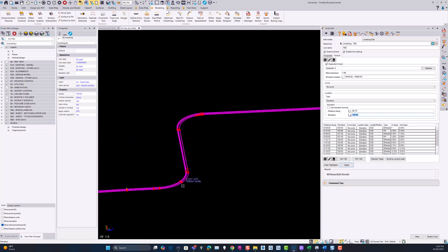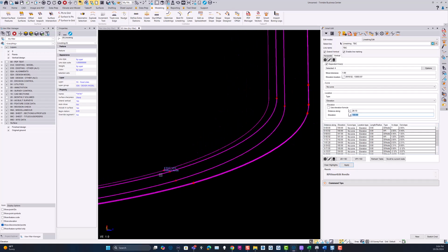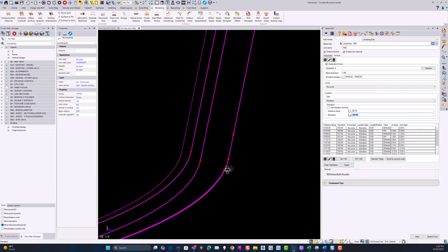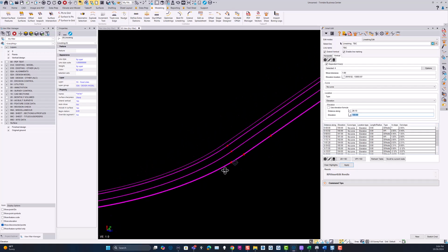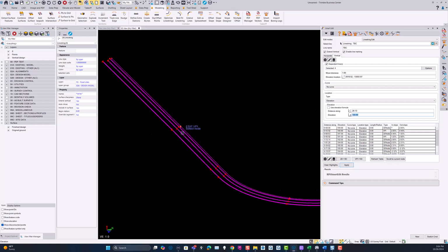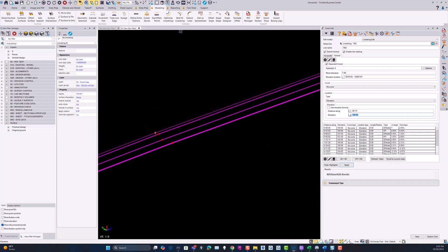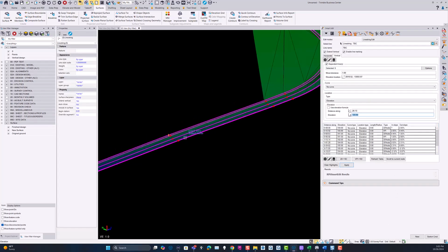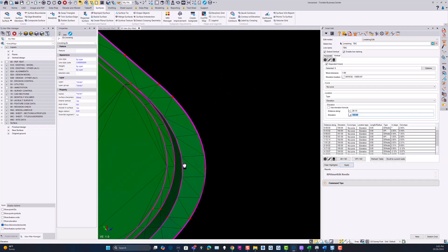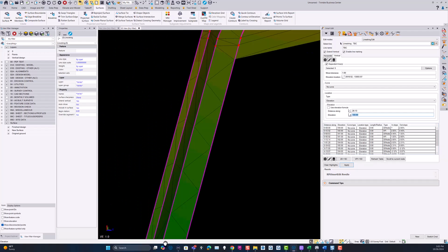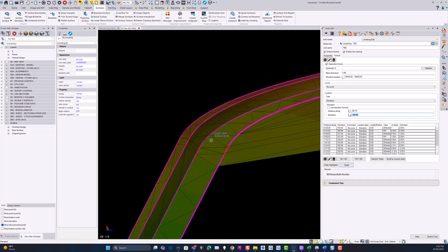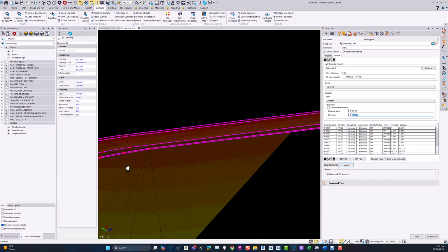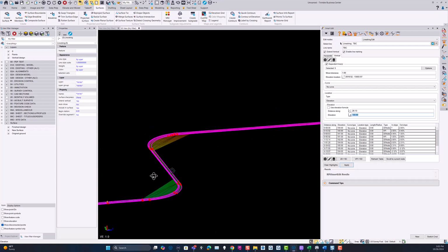And when you look at that in 3D, you'll find now that where you added those elevations, the geometry between them is still the same as they were on the original locations, but now you've got everything calculating out and holding your geometry according to what you wanted. So if I now build a surface model out of those, and then pick these lines here and say, okay, add. Now we've got our curb and gutter section, and each of those edits we made is making the same edits to the lines all the way along here, so we're keeping the geometry consistent between all of those lines as we make those edits into the main line.